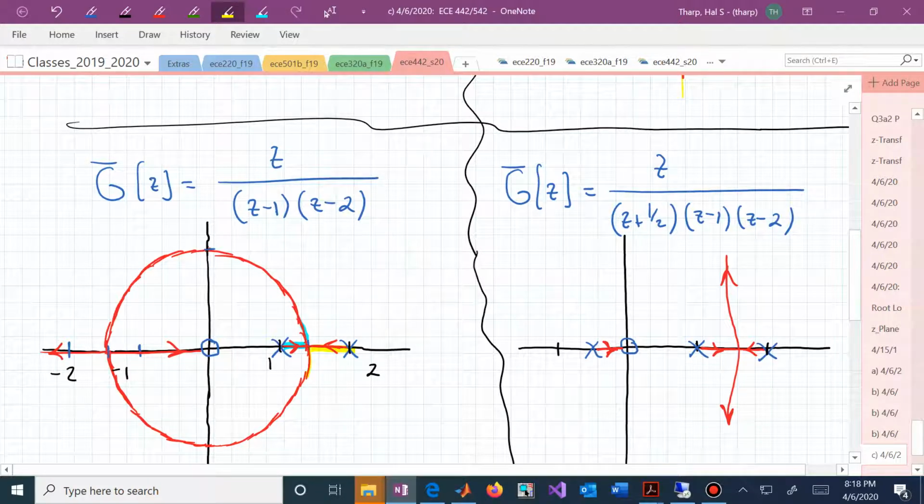What happens next? Well, what we will learn is this particular root locus breaks away, and one goes around to the bottom and one goes around to the top. And in fact, it's a circle with the radius of that circle determined from the distance of that 0. The 0 is the center.